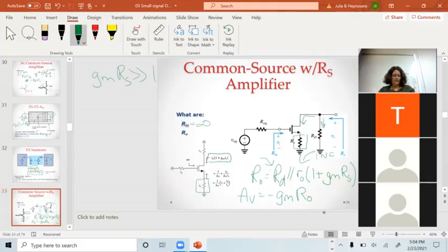I should not go into this. I'm going to go heavily analog on you. Some of you will understand this, probably not many. The purpose of that source resistor is that it actually provides feedback in the circuit. Maybe kind of hard to see. It's going to decrease the gain and it increases the stability. And there are tricks to work around that.